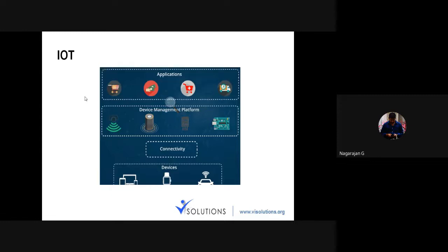We have various connectivity layers over there. If you see here, we can go for USB based communication, you can go for Modbus based protocol to have a data transfer, you can go for CAN protocol, or if you want wireless connectivity, you can go for Wi-Fi, LoRa, or Zigbee. So you can interface with any application, any modules, or any small devices embedded in the objects over there. This is what we call gateway architectures.